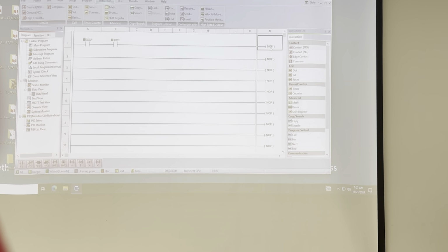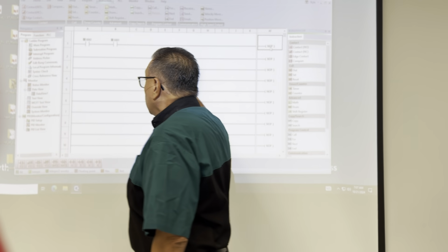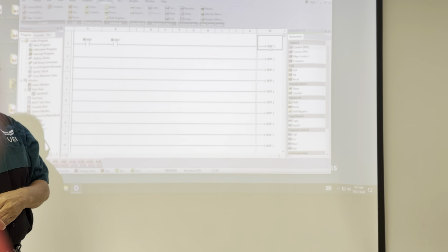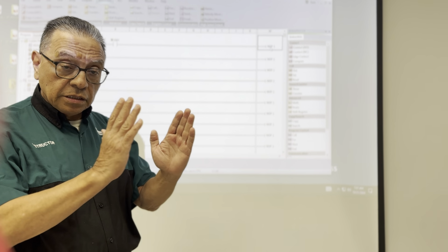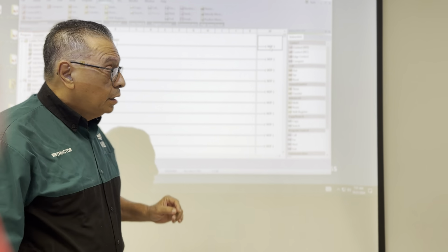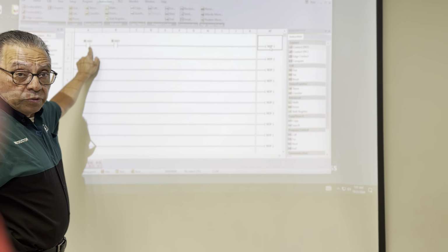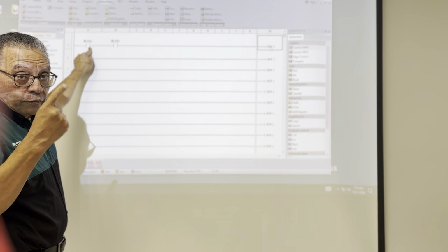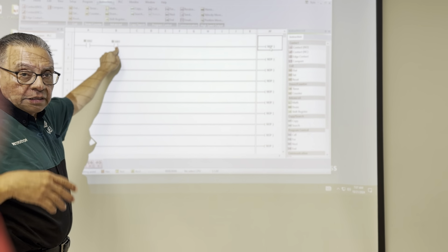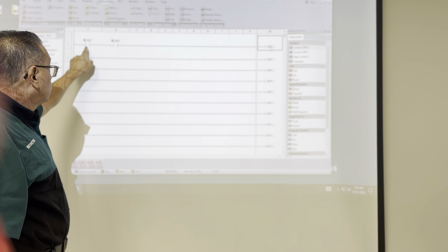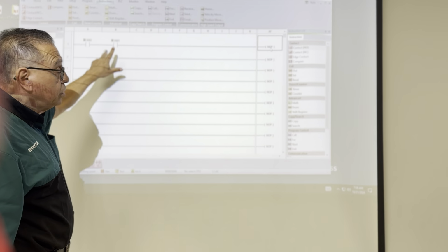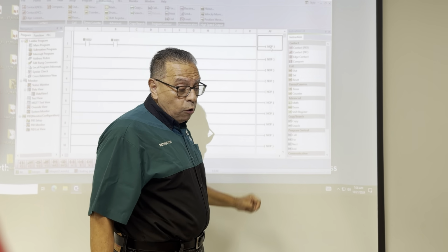And then on the output section, keep in mind, I was telling you that this is my condition area, which means that when I have this, it's an AND condition. It means that both conditions should be met. This input at the hardware level is collecting the information from one switch, and this one is collecting the information from the second switch. This could be a thermostat, this could be a motion sensor. So both conditions should be met in order to have an output.